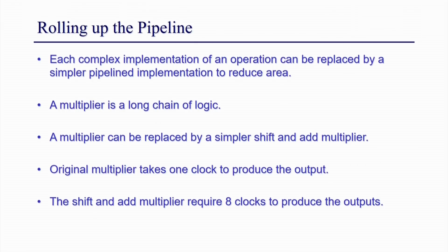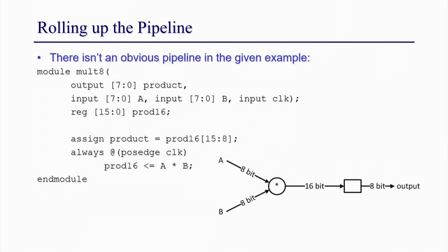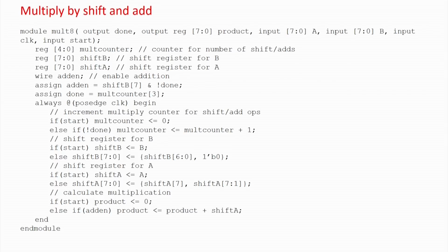Okay. So, there is another aspect here: sometimes your design may have no pipeline, nothing, but there are some complex operations like a multiplier, but you can think about an alternative implementation of a multiplier, which will actually give you better benefit, right. So, that is also possible. For example, suppose your implementation has only this multiplication A into B. So, you effectively have a multiplication, which, if you assume, is a big complex implementation, because it will finally be mapped to logic, right, and it will take a lot of gates. But if you think about it, I am going to implement multiply by shift and add, right.